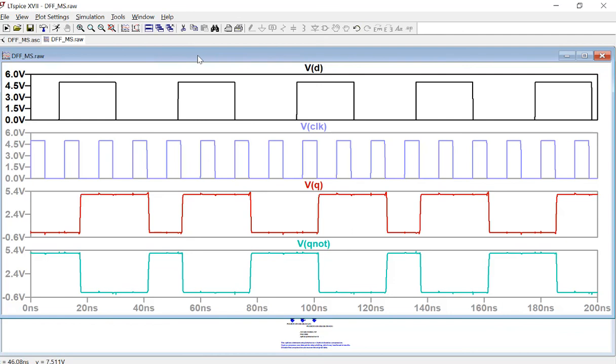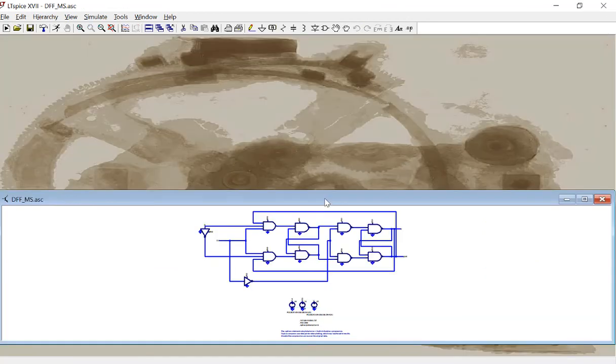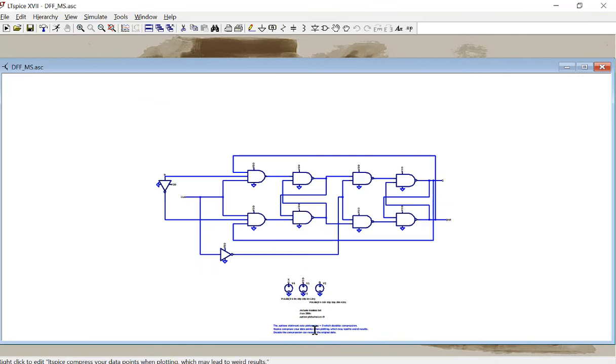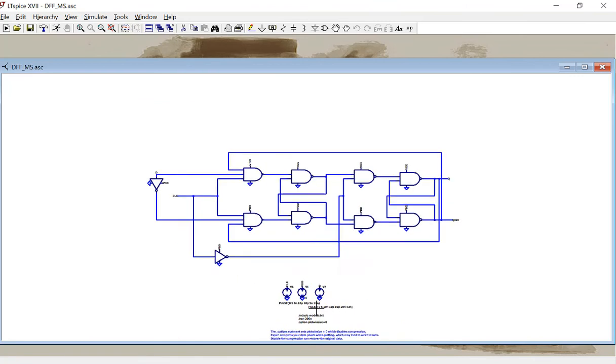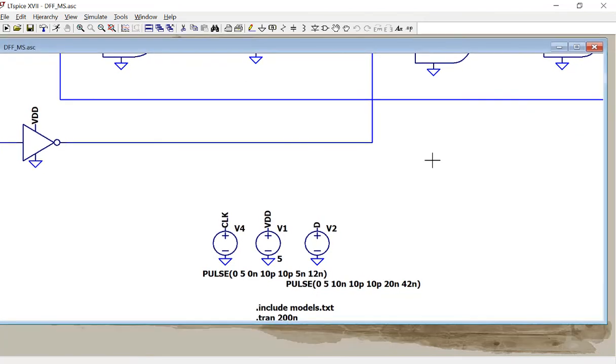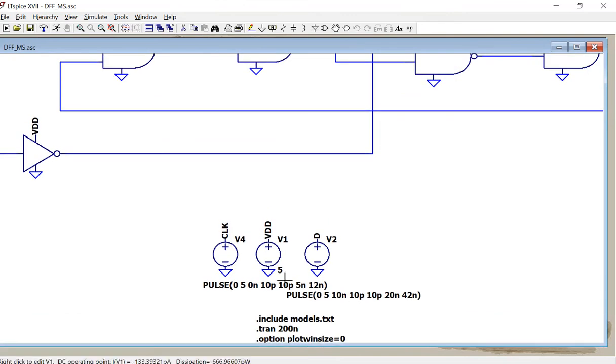All right, so what you need to do is replace this guy with a 3 input NAND gate and add a set and reset. And after you run this simulation, let me show you the code. What's the code? The SPICE code. So you know what I used here. So these are the SPICE code. If you watch the video, you can directly use the same thing here.